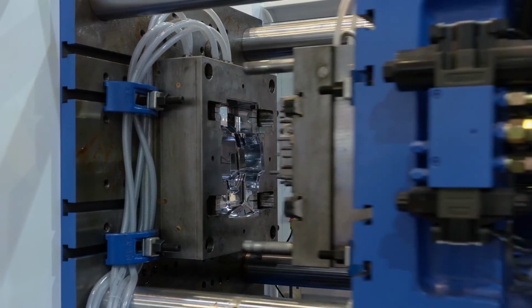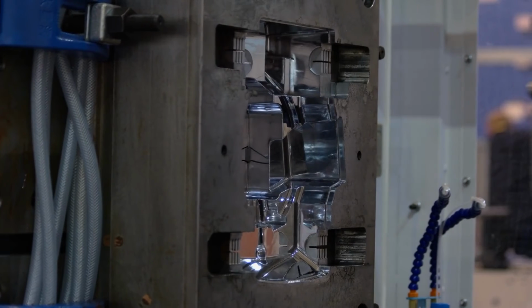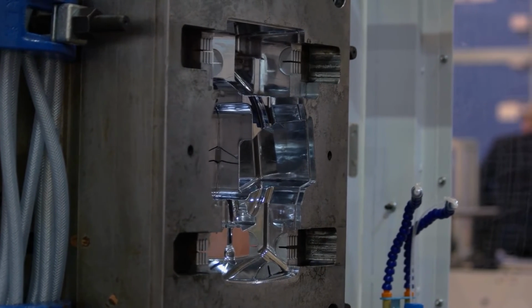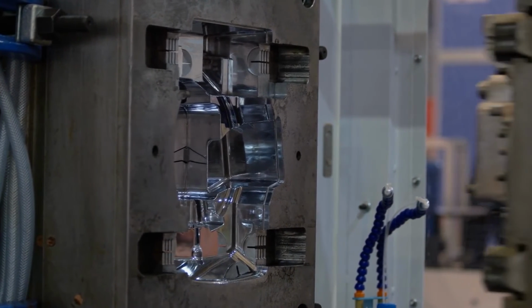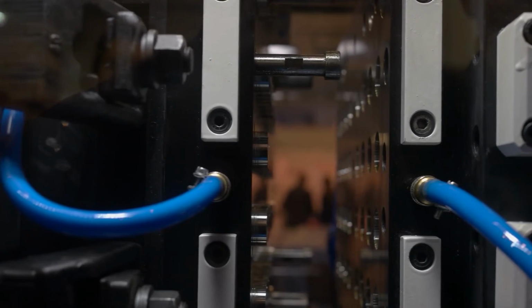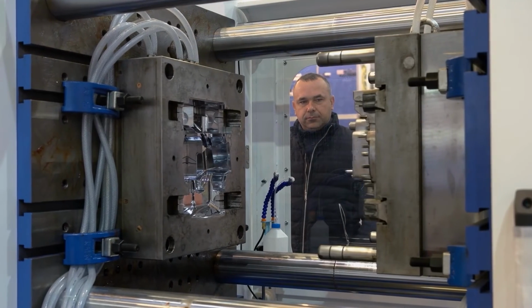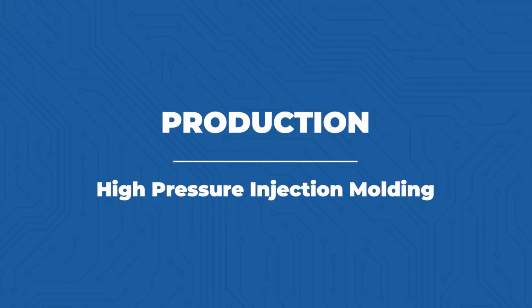They inject molten plastic at high pressure into this cavity, and the high pressure is used so that the molten plastic goes into every little nook and cranny of the cavity that forms your part. The plastic is allowed to cool, and then the mold is opened up and the part is removed. It sounds really simple, but there are a lot of complex restrictions on injection molding, and I'll be getting into that in more detail shortly.